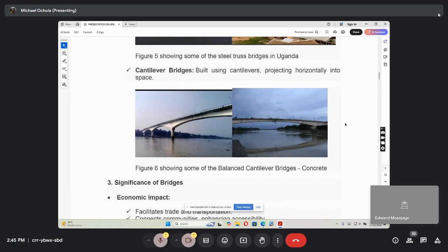They call it uniform depth. Then as the span goes more than 70, 80, then they begin to vary the depth. Then this is now where you go to reinforced concrete. You are going to use elements of reinforced concrete, basically reinforcement bars, but you also have additional cables, post tensioning with the strength of 1860, 5 times the normal strength of your normal steel bars. So we can learn about that, and you'll be happy about this one.